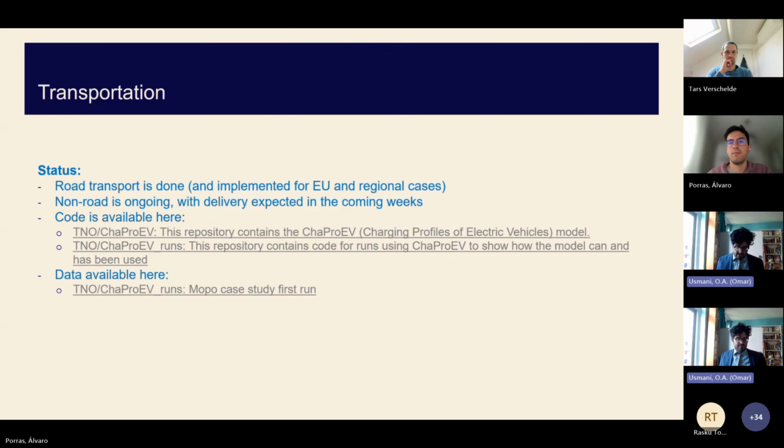Once you have those scenarios defined, you compute a mobility matrix, mobility patterns, which tell you at each hour, which is the resolution, where the vehicles are, if they are moving from one place to the other, if they are parked, if they can charge, etc. That gives you a mobility pattern. From that pattern, combined with the vehicle properties, you can figure out a consumption. The baseline is electric, but of course you also have equivalents in other fuels, so we can also provide weekly or monthly or whatever consumptions for other fuels. And then we focus on the electric part.